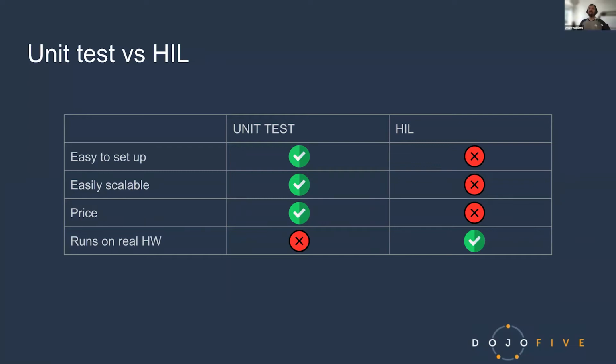But yeah, usually when you have to automatize something on your setup, it could be some really small tests that you do, or it could be some verification thing that you do. Even if it's really small, probably that's your first step into hardware in the loop. And how to start with this? Probably the best thing would be to start with unit tests, because again, it's easier. And then you can start building your mindset around how to make it modern, how to test the stuff automatically.